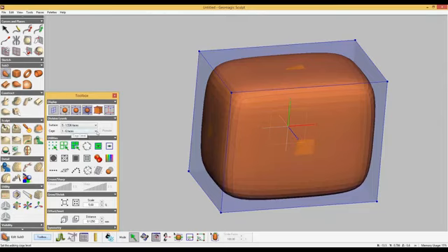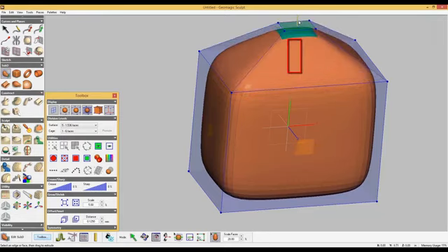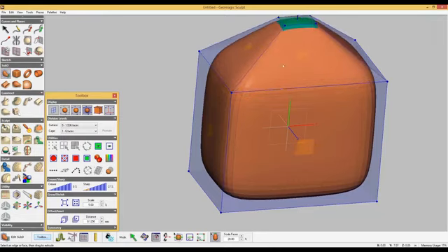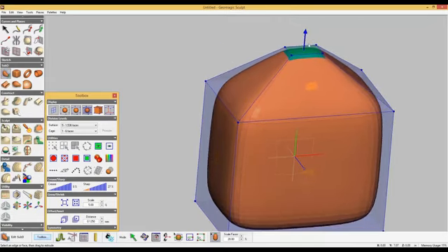Start changing the shape to a gas can. First, select the Extrude Edge or Face tool in the Dynabar. For scale faces, enter 20%, meaning a new face will be 20% of the size of the face you select. Click on the top of the shape. Click and drag the vector arrow and extend the top face. Here I'm going to about 3.6.